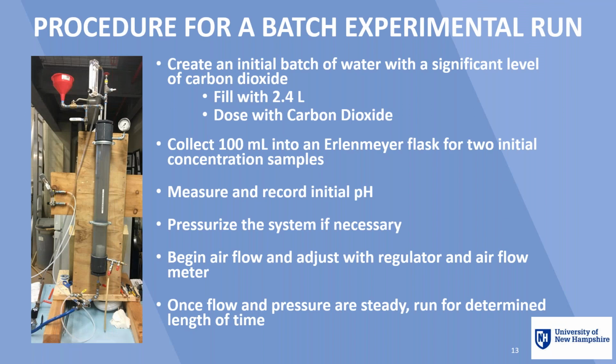So the first phase of the research was batch runs. The experiments were batch runs, and the general procedure went through these steps. First, an initial batch of water was created with a significant level of carbon dioxide. The vessel was filled with approximately 2.4 liters and then dosed with the carbon dioxide from a supply tank.